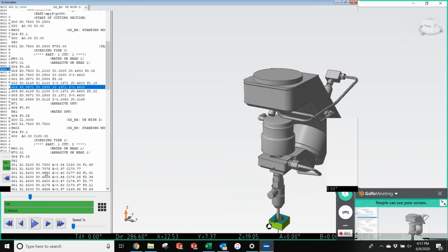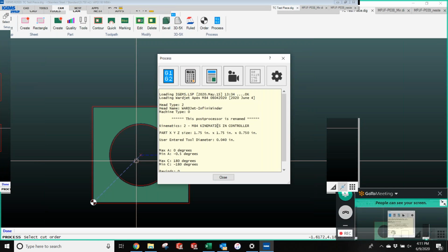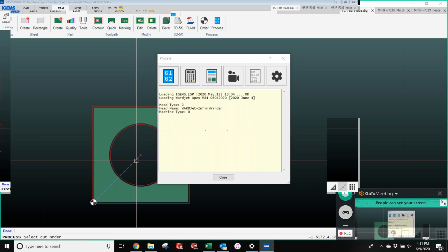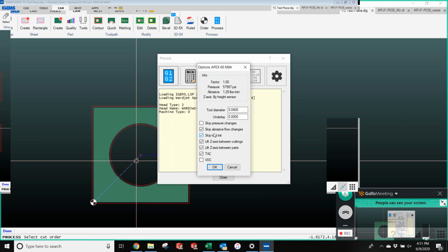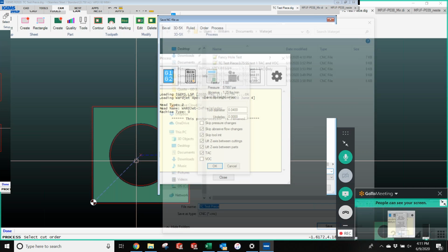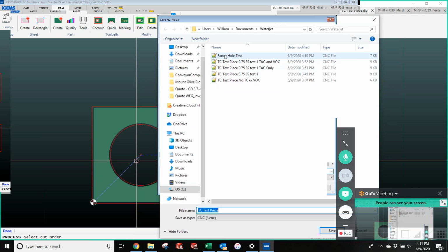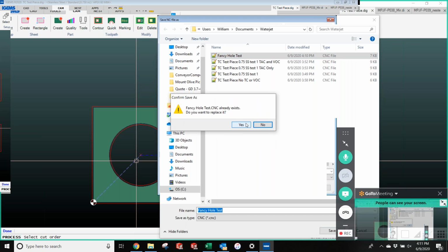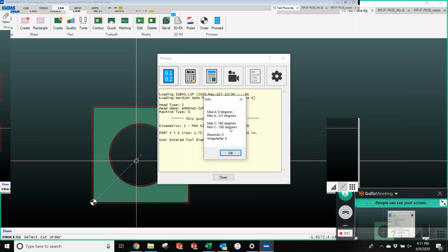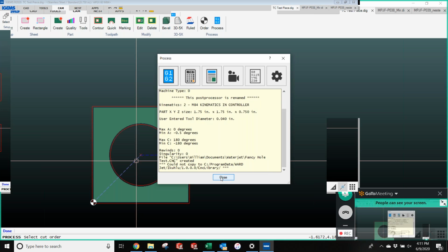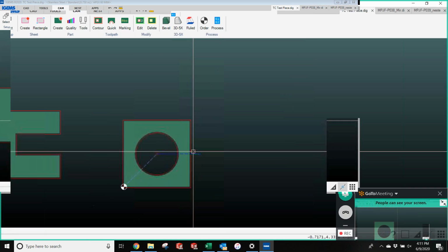Does a rewind really hurt anything, or is it just a stop and start point? Yeah, start and stop. So you'd see a little bit of a blemish there where it re-pierced. Just a little witness mark. Right. Yeah. Okay. So if it's not a critical edge, then you could go with it. Obviously, if it's a critical edge, then you'd want to change things. All right, please hit yes. Okay. So you could try that, see how that looks out of 3/4 inch.